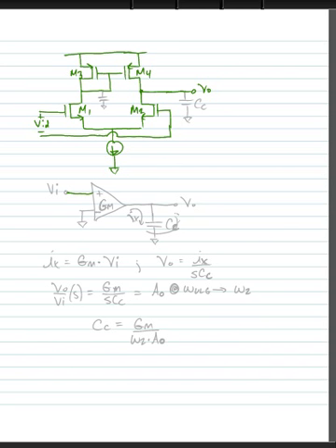So here, we're just going to treat our op amp like a GM. We're going to put an input voltage into the non-inverting terminal, and we're going to add a compensation capacitor to the output here. Now remember, this particular topology does typically have two poles in it. It has a pole due to the output node and a pole due to this current mirror node where we have some parasitic capacitance. And you've solved for that in some of your homework examples.